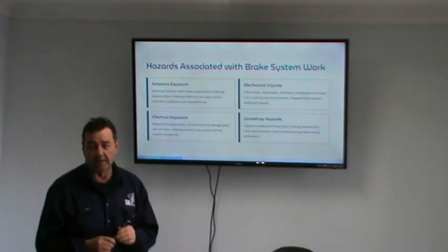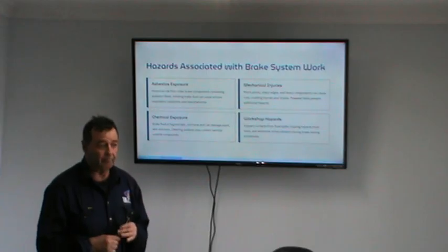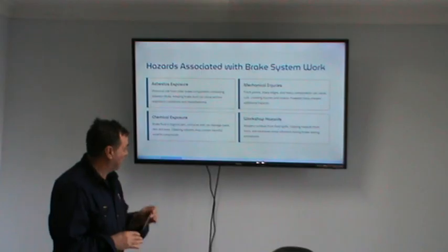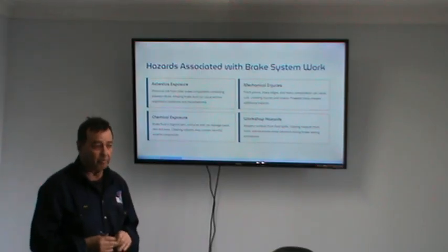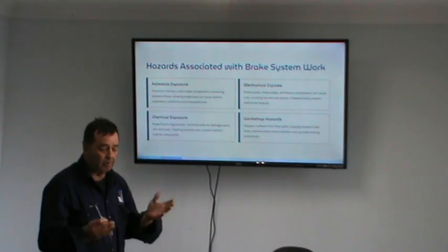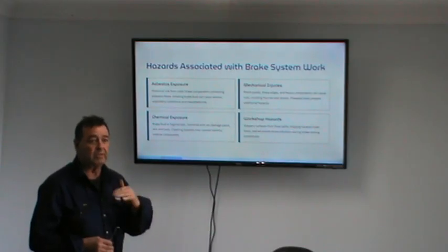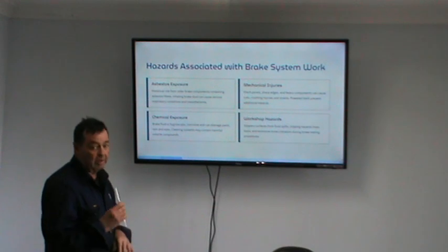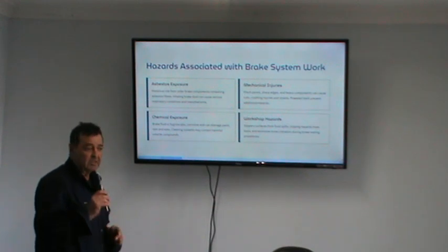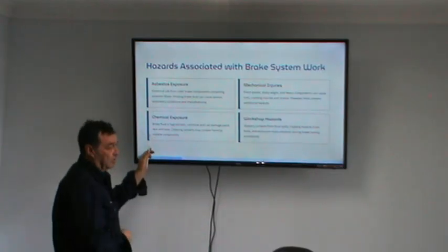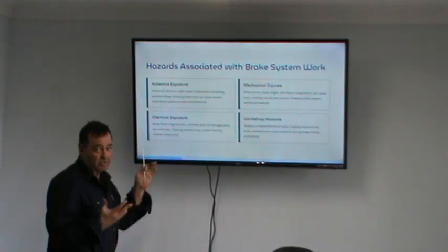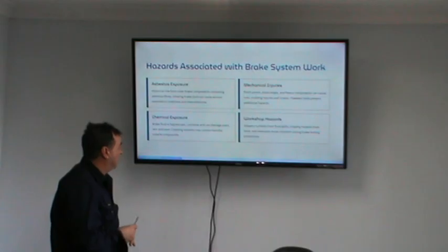So we'll talk about that later when we do our inspect on the brakes. So we talk about hygroscopic, then we talk about the boiling point of brake fluid. Once it becomes hygroscopic, once it gets moisture in it, its boiling point will lower, so it will overheat quicker. But that's another subject. Gets on the skin, you'll get skin irritation, gets in your eyes, it'll cause damage.